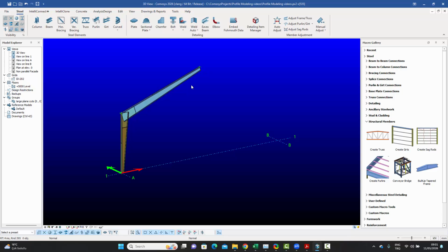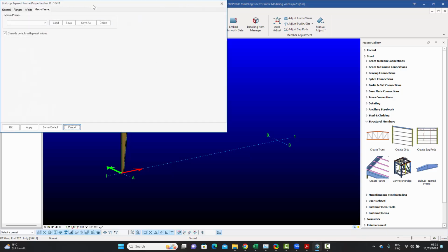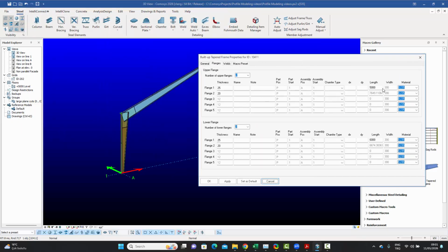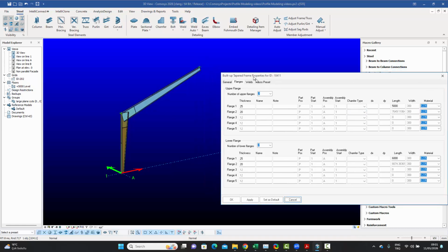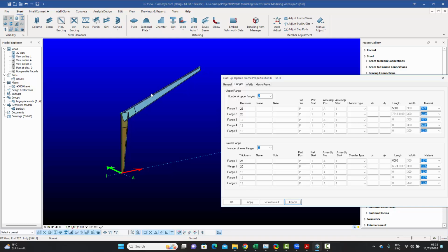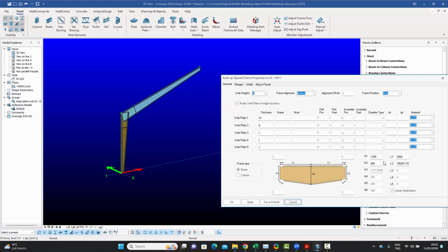Once you've got these typical presets saved away, you can easily load them and then play with these numbers. Let's say you're doing a different one, and the basic format is the same. One change is, or two places where, two thicknesses for the top flange, two thicknesses for the bottom flange, and two thicknesses for the web. You've got that saved away. All you need to do is just change these numbers in some other application which you might be doing, and you can use the same presets repetitively as well if you want.